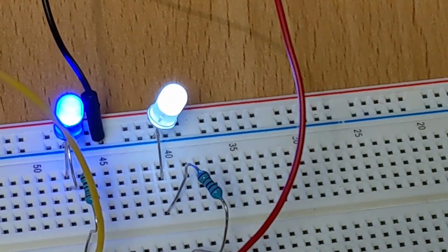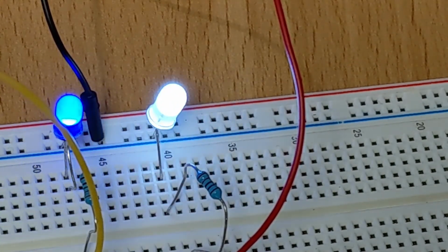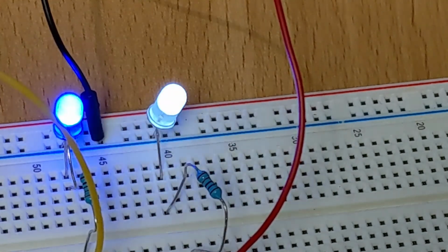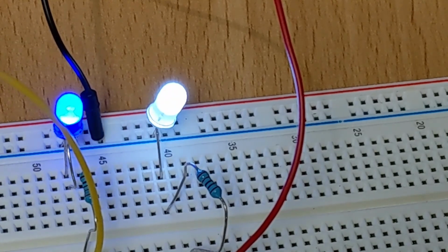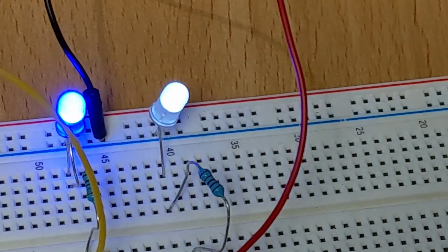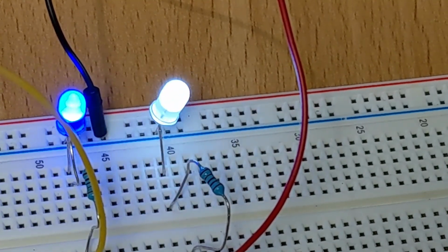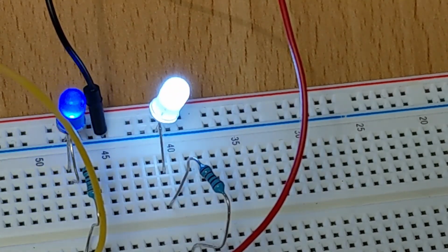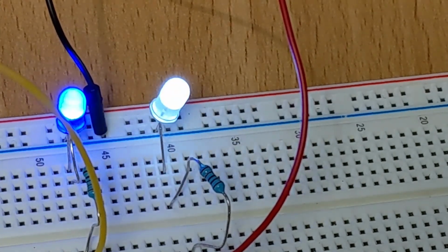Okay, so I've got a little bit of a confession to make. It didn't work first time. What was going on? Because I was pretty sure my code was good. It turned out that pin 12 and pin 13 aren't set up for pulse width modulation. If you look at your board, numbers 3, 5, 6, 9, 10 and 11 have all got a little squiggle in front of them, and that means that they can do pulse width modulation. And like a twonk, I completely forgot about that, but it happens sometimes. You can see it's working now: the blue one is going down, and the white one is going up in brightness. Happy with that?